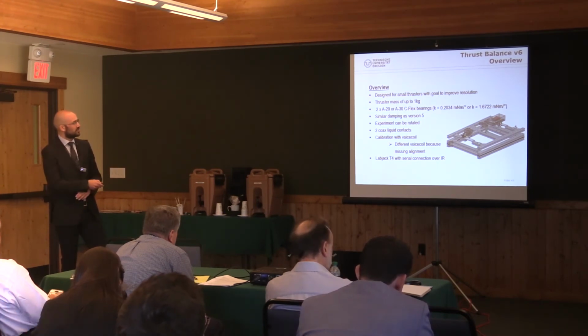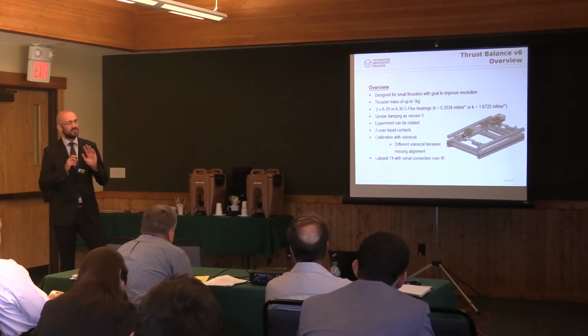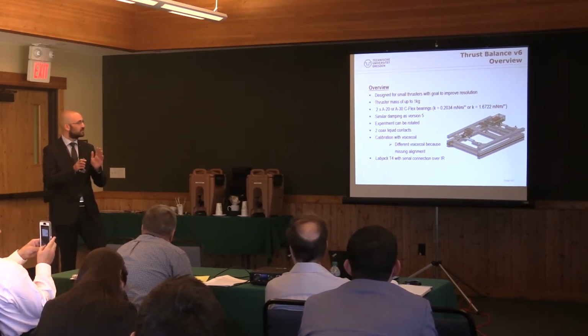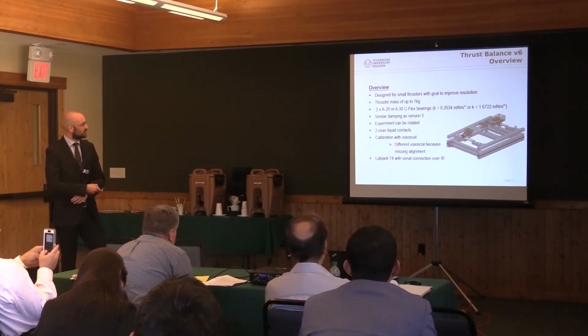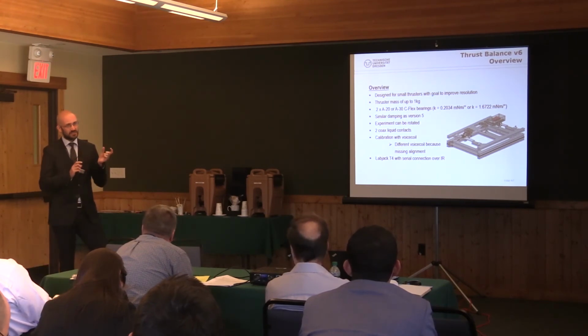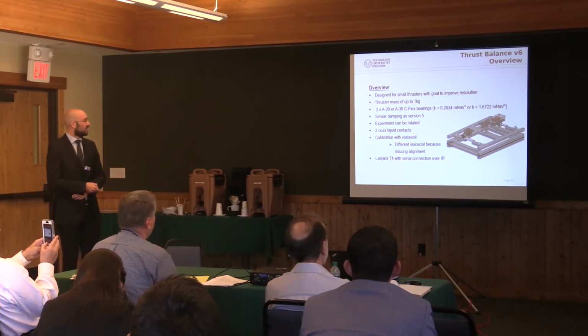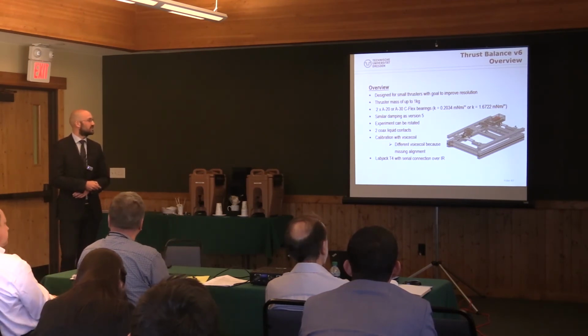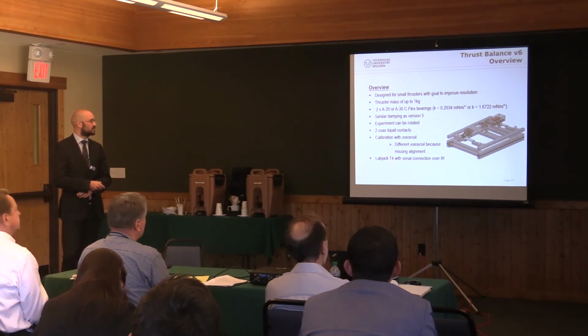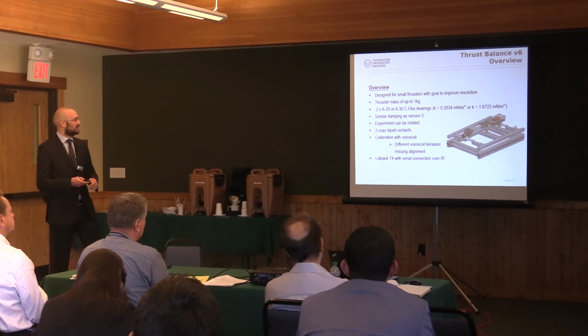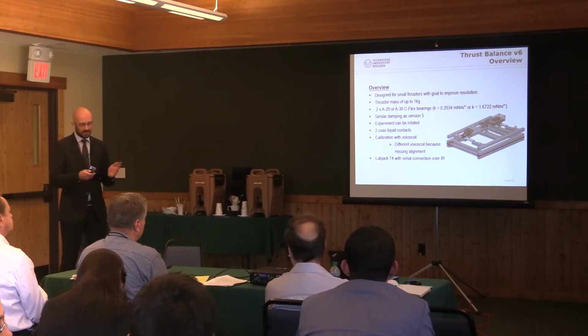A little bit a different one, because in this measurement we don't have this center motor where we can align the voice coil where it's supposed to be. So we use a voice coil that has 6 millimeter range. So we have to set it up a little bit more carefully. And for all the data acquisition and so on, we use this time a LabJack T4. It's basically the same, but it has a few fewer analog inputs and so on, and it's smaller.